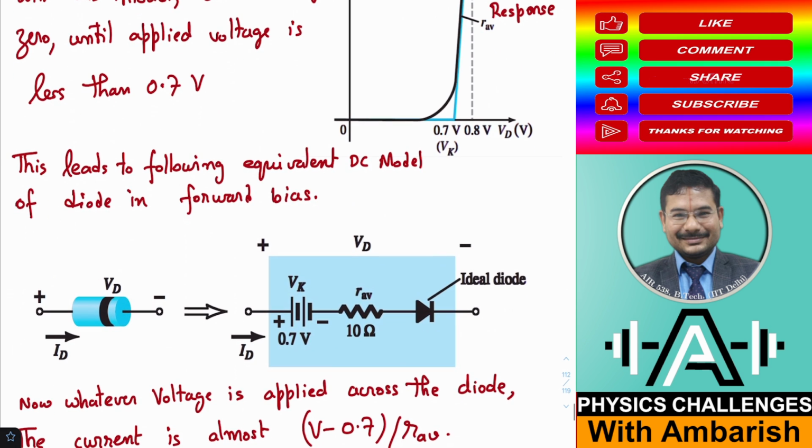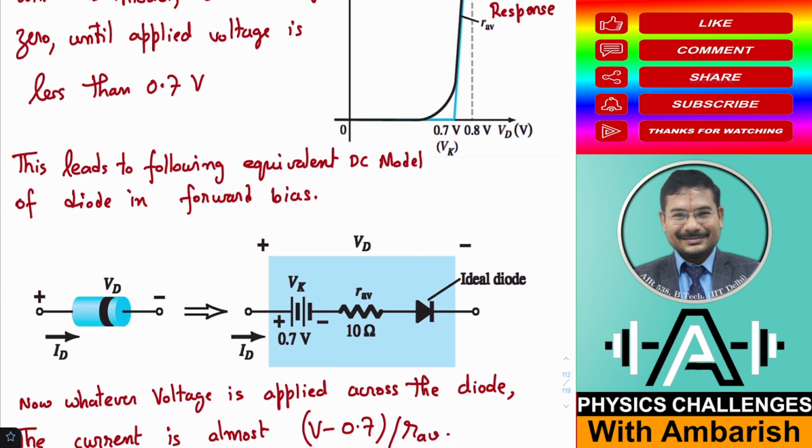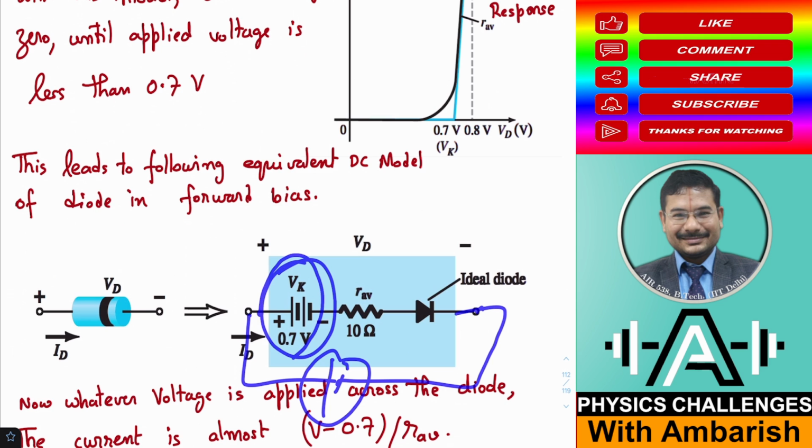So this leads to the following equivalent DC model of a diode. You put a reverse battery of 0.7 volts, and then you put an ohmic resistor. You know that straight line behavior can be easily modeled using a battery and an ohmic resistor. Suppose you apply 3 volts over here. Out of 3 volts, you have to subtract this 0.7 volt. So the current will be 3 volt minus 0.7 volt, that is 2.3 volt, divided by this 10 ohm.